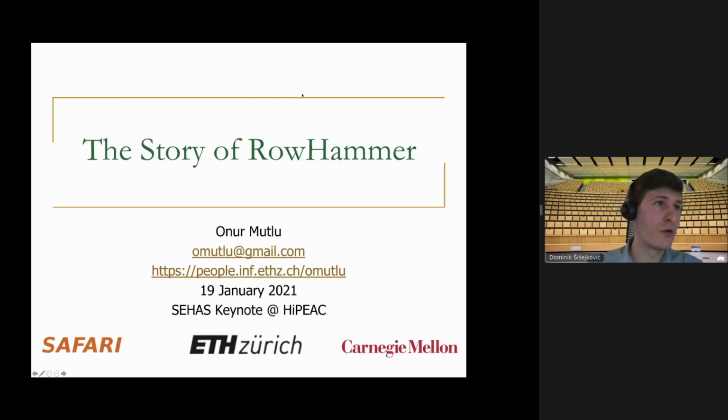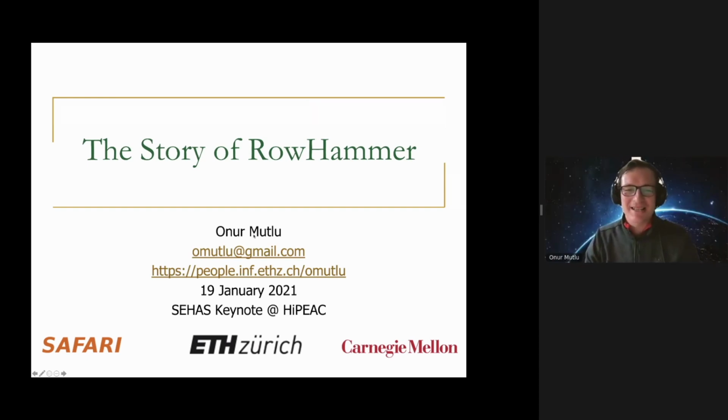His question is, would randomly swapping rows during refresh help, building on the defects handling logic already present in DRAM chips? Yeah, so that's a great question. I think there's a potential for this. You need to have enough spare rows to actually do the copying of the hammered rows. But I don't think random would work, frankly. Random is a bit difficult.